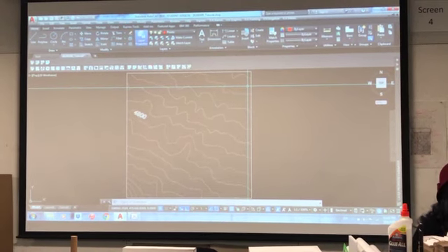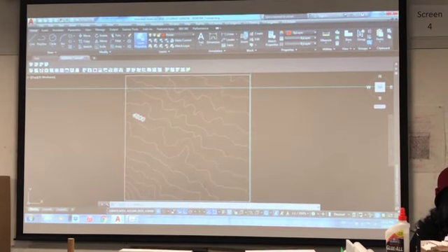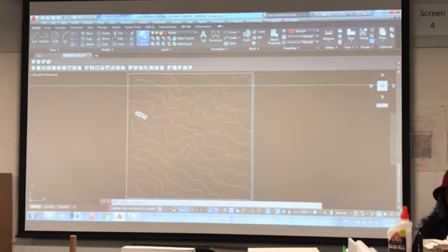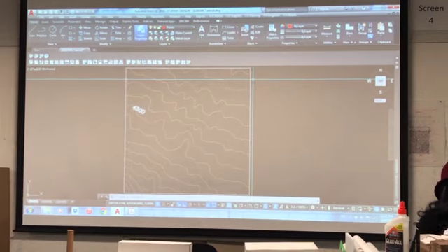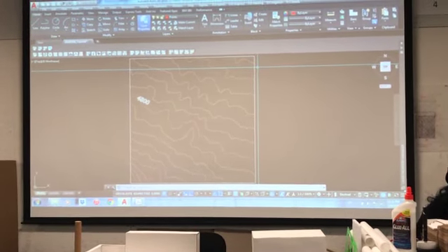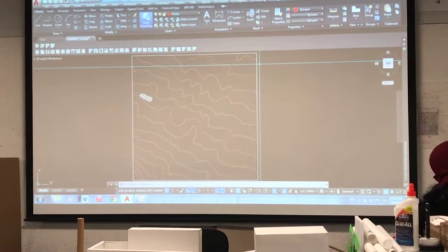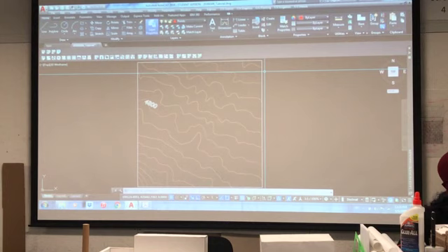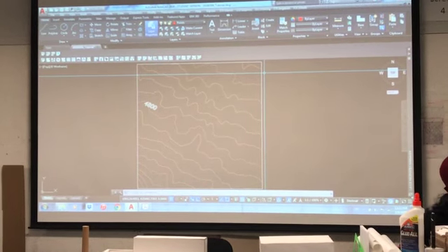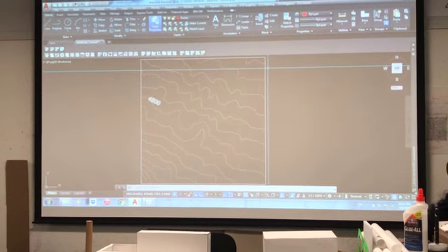The way that you can verify that is by continually tracing, or just following visually, the lines on the overall topo and seeing where the next highest or lowest elevation marker is. Okay? So you can either know one of your elevations and know which way it falls, or know 2 of your elevations and work from that. Okay?